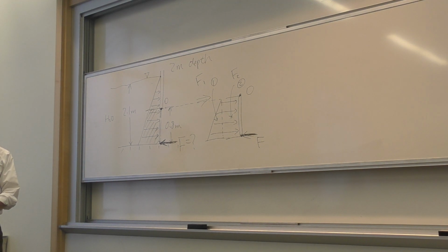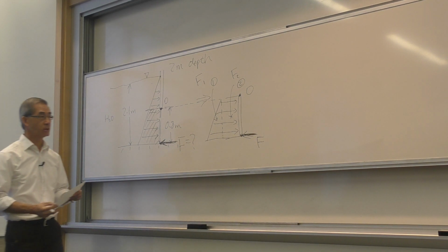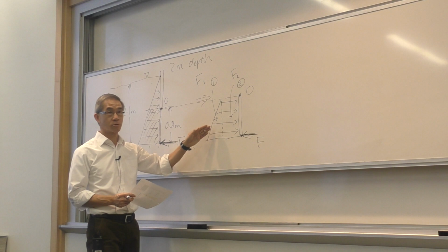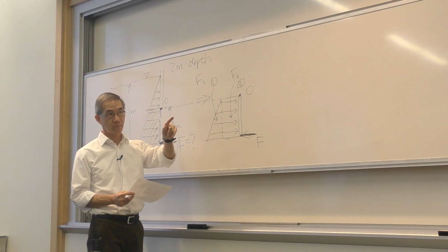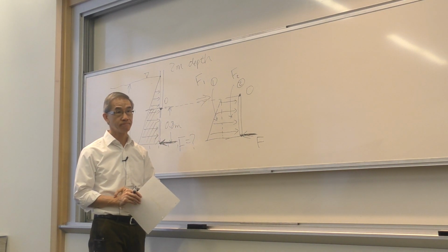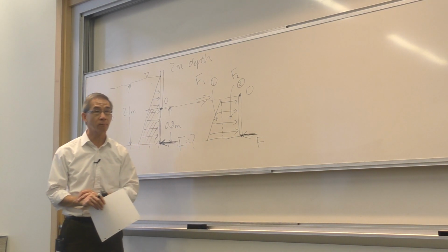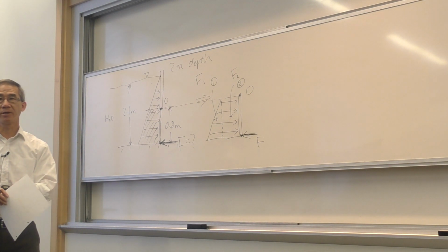Any questions? Yes? So in this case, for the pressure from the water, you can no longer use 1/2, right? You have to solve for the average and just that 0.8. Yeah, the question is now the next step. How do we proceed to solve the problem? So that is what we're going to do next. We're going to do the rectangle first, and then we're going to deal with the triangle. And to answer your question, to deal with the triangle, I will basically use the same approach we did last time, in the last lecture. And then when I come to that part, your question will be answered. What is the average pressure now for this new triangle? It takes a little bit more twist, but it's fundamentally the same.